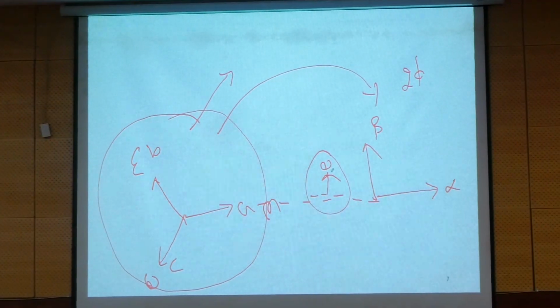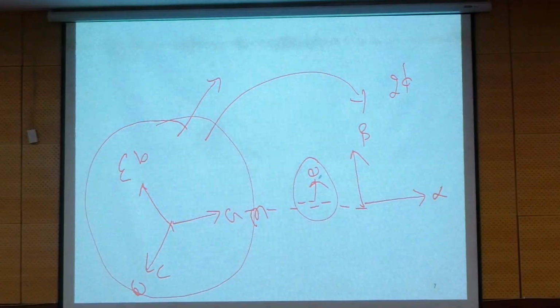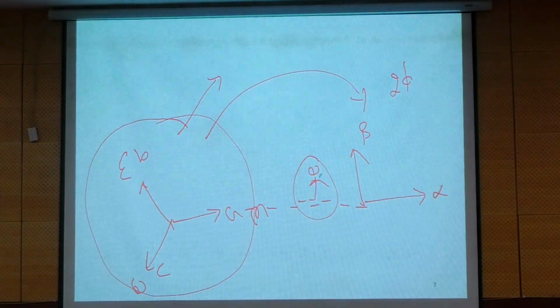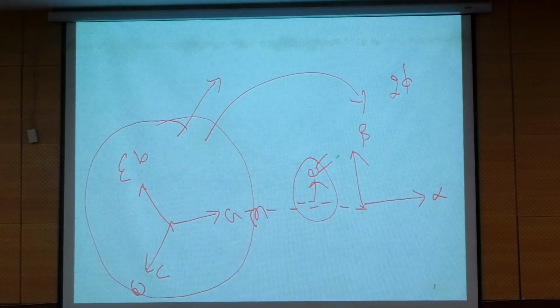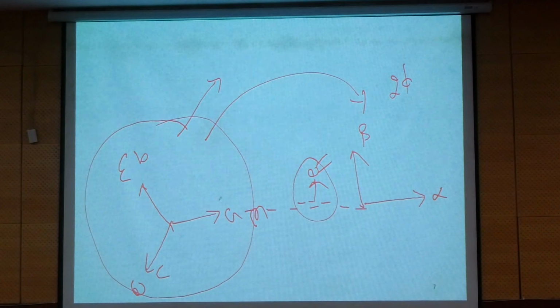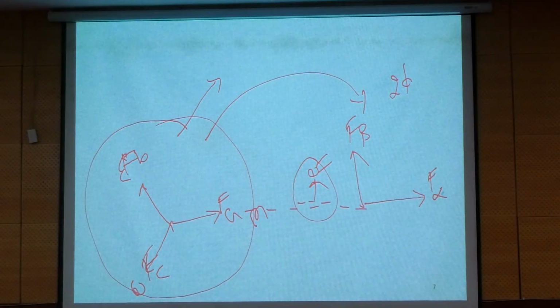This conversion matrix is so important while transferring the variables from three-phase to two-phase without losing any property. So with respect to this phasor, what is the mathematical model for A? Let us say this is FA, FB, FC, and this is F alpha, F beta: A phase MMF, B phase, C phase MMF in three-phase, F alpha, F beta in two-phase.